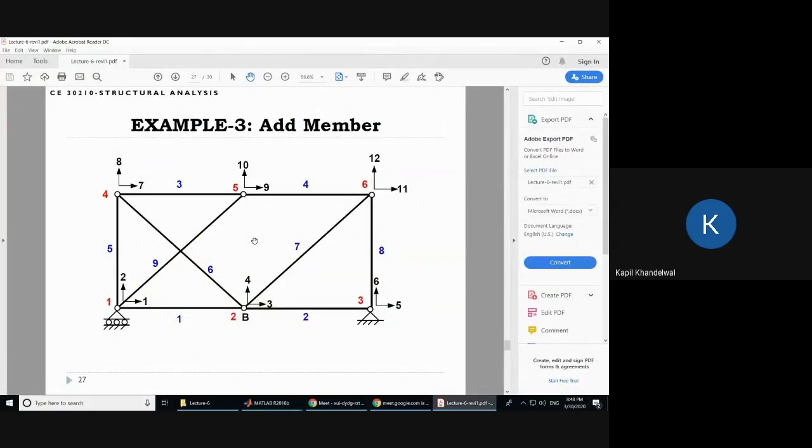should be greater than 0, and the corresponding eigenvectors should be strain inducing. Okay, so those are not corresponding to a rigid body mode. And whenever you have an eigenvalue that is 0, that will actually correspond to an eigenmode that will displace a structure in a rigid body mode. And the rigid body modes can be both global, so globally the structure can move as a rigid body, and can be local, so only a part of the structure can move as a rigid body. Okay, and both of these things should not be present in any kind of